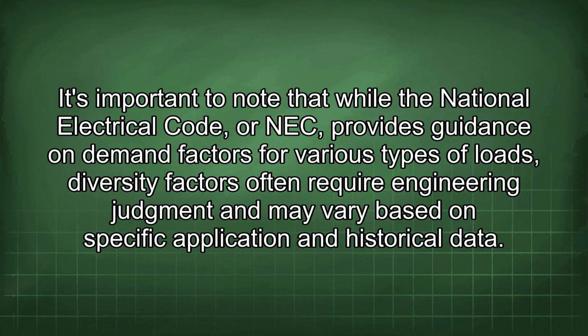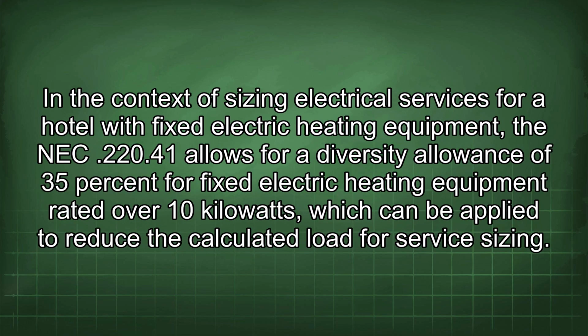It's important to note that while the National Electrical Code, or NEC, provides guidance on demand factors for various types of loads, diversity factors often require engineering judgment and may vary based on specific application and historical data. In the context of sizing electrical services for a hotel with fixed electric heating equipment, the NEC 220.41 allows for a diversity allowance of 35% for fixed electric heating equipment rated over 10 kilowatts, which can be applied to reduce the calculated load for service sizing.